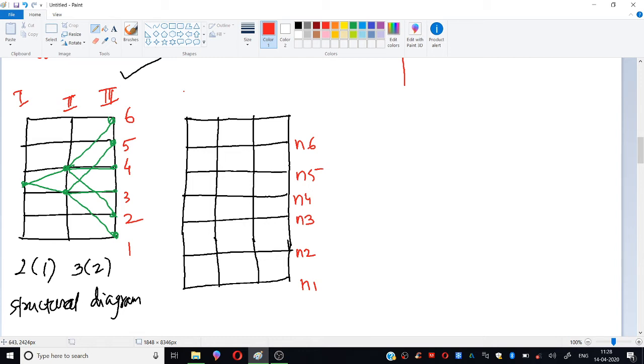Now this is shaft 1, this is shaft 2, this is shaft 3. Now what about this point? It is the motor shaft, or through this point we are going to get a direct speed from the motor. Now, as already described, the ray diagram is a representation of the structural formula, and it shows transmission between the last shaft and the preceding shaft. This is the most important thing, that it shows you transmission.